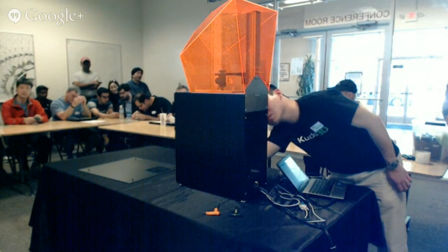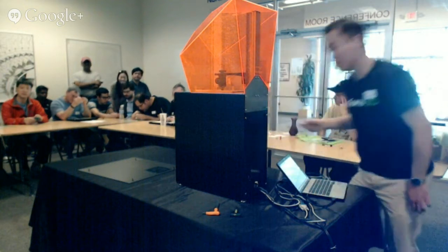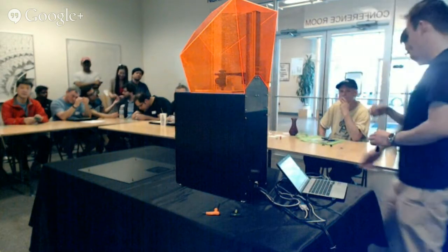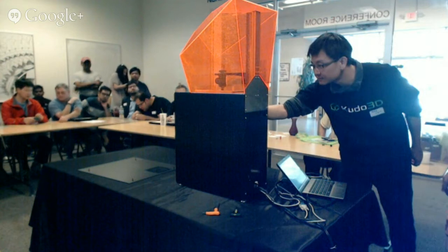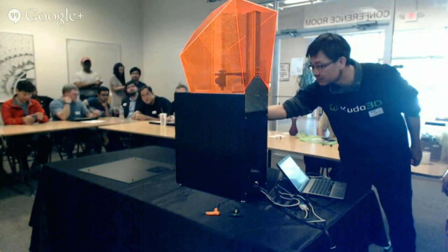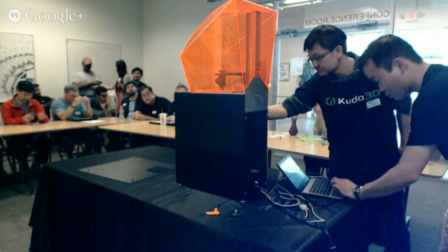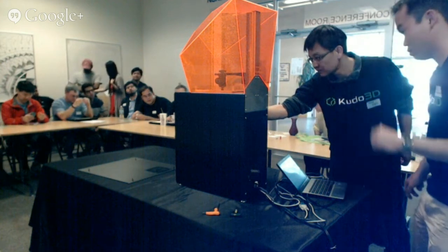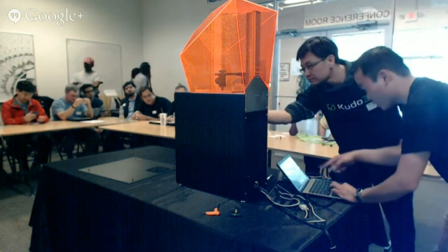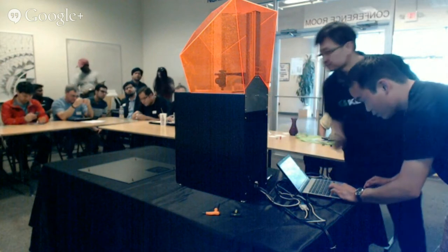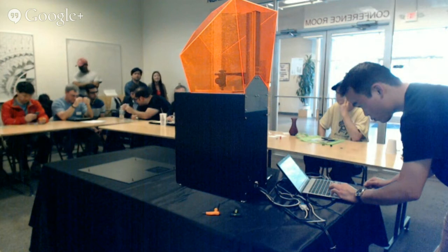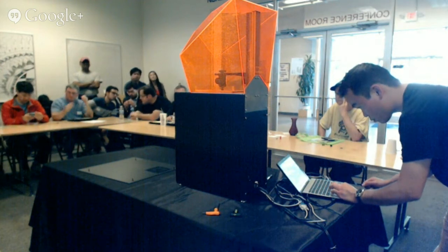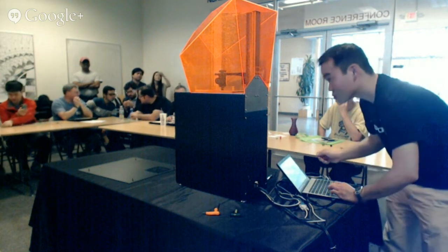There's a couple of different resins that will hold up, but you've got to hold up to the temperature. Most people do in their ovens, like around 350 Fahrenheit. So it's got to stand up to the temperature and to the pressure of being clamped in between the two rubber halves. You're going to cast something in resin. Do you know if this is reactive to silicone casting rubber? I mean, almost nothing will work with a platinum catalyzed, but I'm betting with most tin catalyzed silicones, it'd probably be okay.